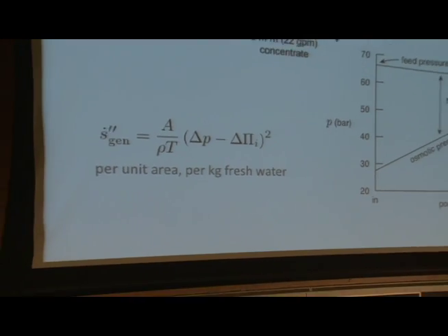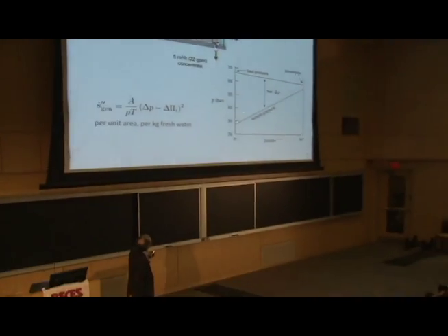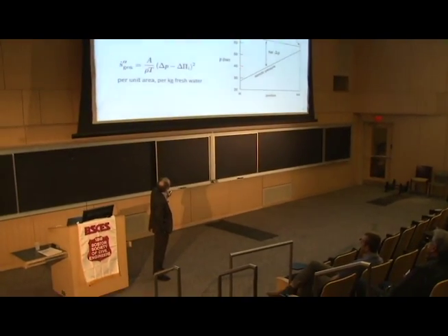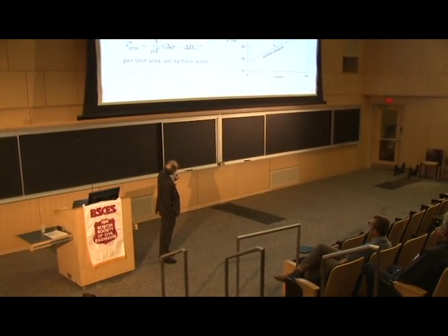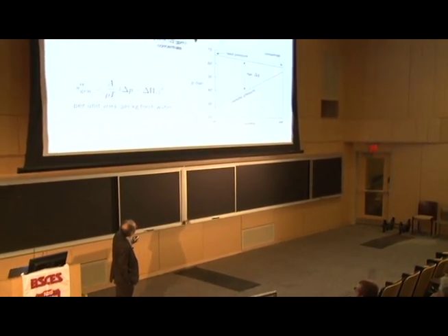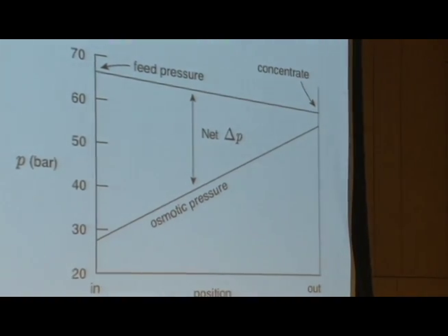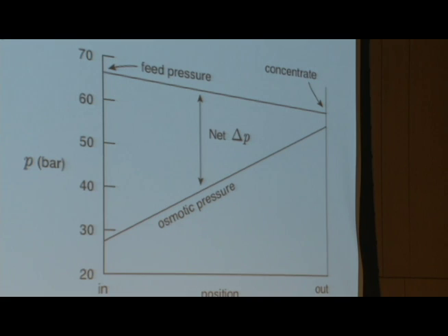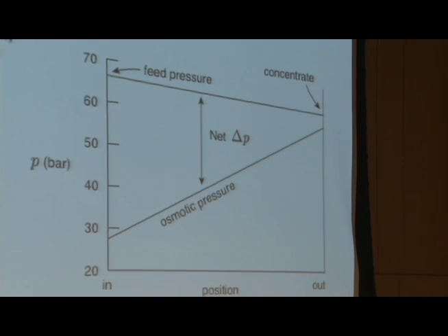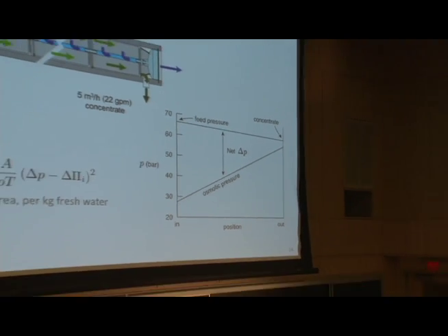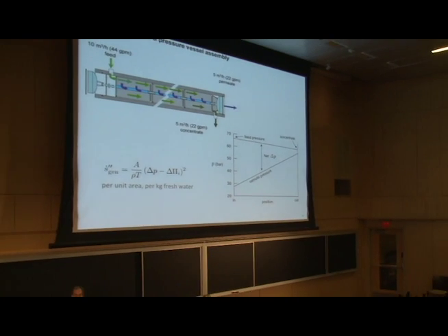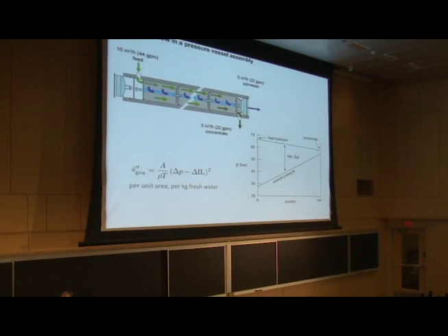Well, one thing that you might consider doing is coming in and saying, well, how about if I just pressurize to 40 bar and let the pressure drop, and then I have another pump and I pressurize again, and pressurize again, right? You will cut down on the overpressurization, and that will clearly lower the entropy generation. But it will raise your CapEx. And these are large, expensive pumps, and the result is that it's hard to do that economically. You really need to look at processes that work a little differently.